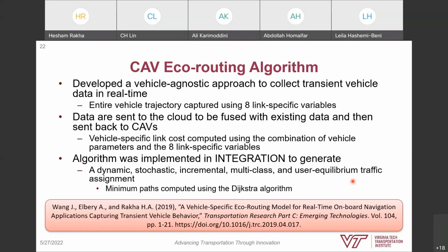So if I'm driving an electric car, the optimum speed for an electric vehicle is around 27 kilometers per hour, so maybe 15 miles per hour. Whereas if you're driving a gasoline vehicle, it is more efficient at around 55 miles an hour. Conversely, remember when we talked about electric vehicles and trains, when you have stop and go conditions, you can regenerate your battery. And so electric vehicles actually thrive on congestion because that's better for the regeneration of their battery.